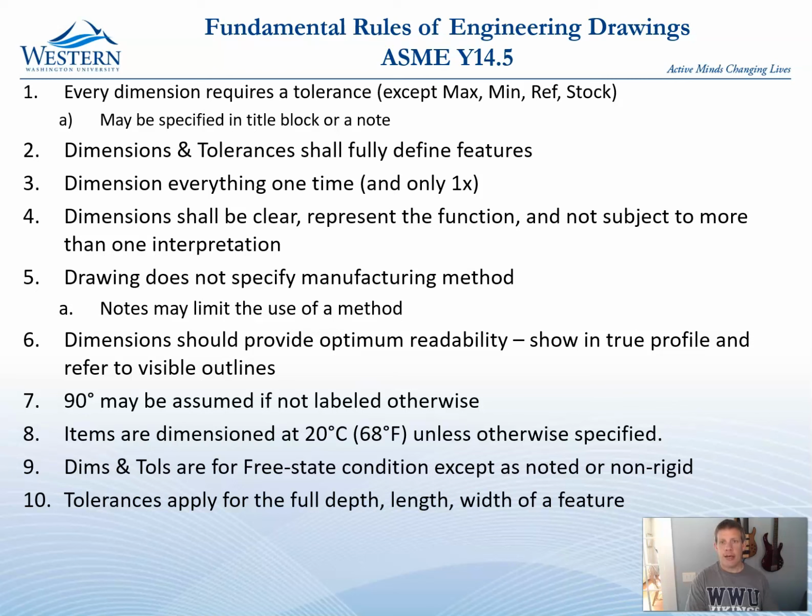and I can guarantee you that if you do not have a call out for GD&T on that hole, when the manufacturer measures it, they are only going to measure it at the top surface, because they don't want to know if the hole is good further down through there, unless you call it out in GD&T. If you call it out in GD&T, then they are going to budget for more metrology time to be able to give you the assurance that the part has met the GD&T that you called out.